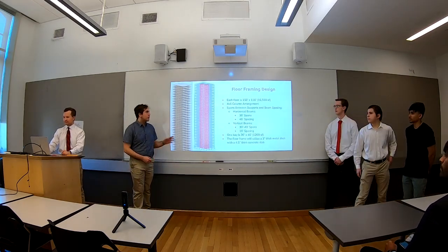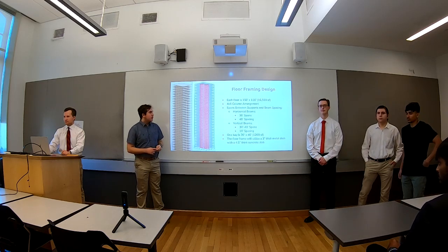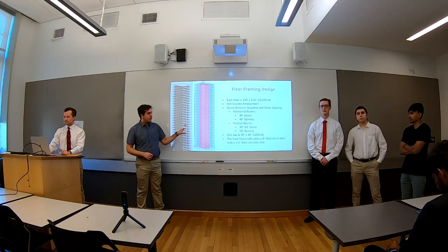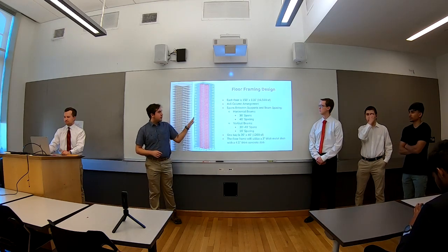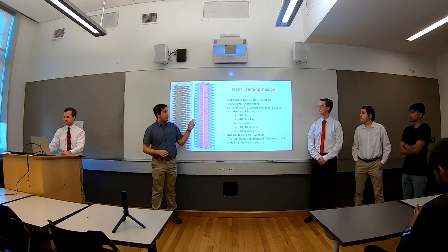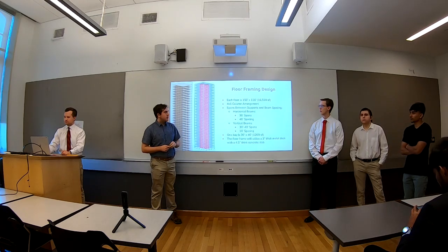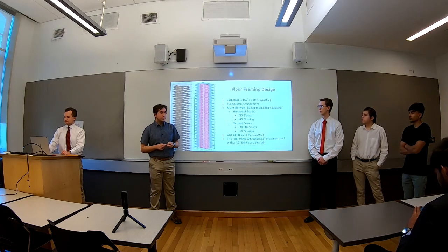Okay, so just some normal dimensions and specifications for each of our floors. For the 40-story building, here's one of the models in ETABS and then a render model. Each floor is going to be roughly 150 by 110 feet, totaling 16,500 square feet. The spans between the supports and beam spacings are 30-foot spans, 40-foot spacings.